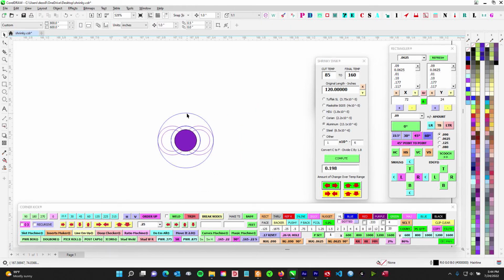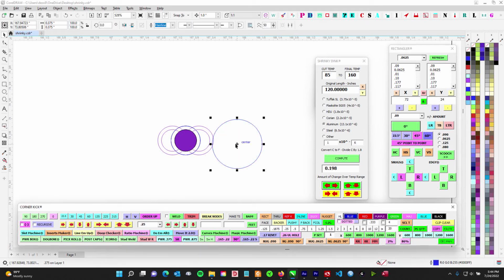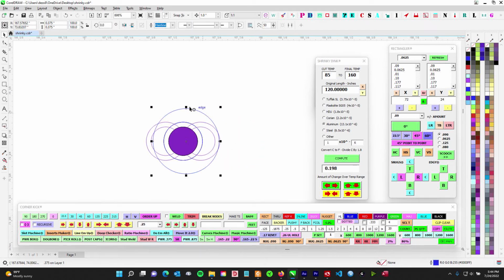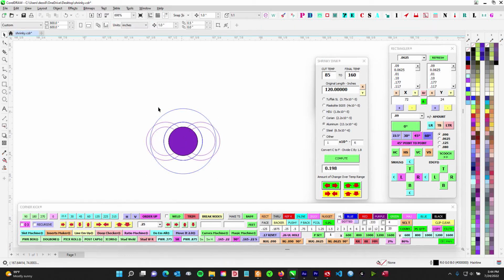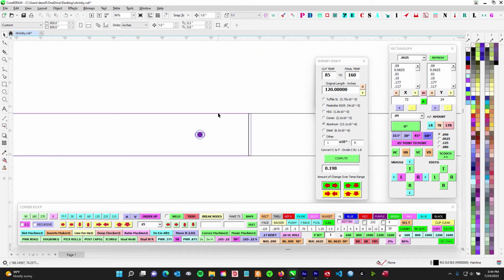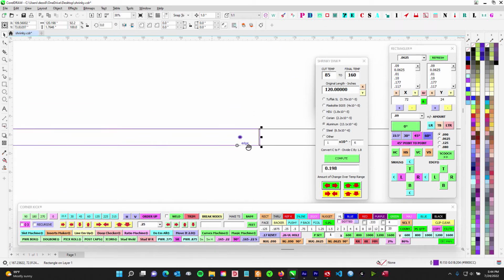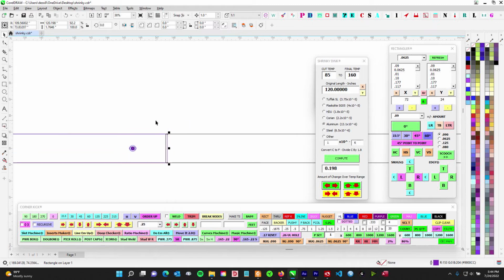So if you were to drill, this is a 0.4. So if you were to take like a 3/8 drill bit, now let's just go ahead and do that. I'm going to hit a 3/8 hole and hit blue. So you can see if you take a 3/8 drill bit and do your hole in the stucco or block or whatever, and then really silicone the crud out of it, you can see where you might have enough room for a bushing. But the fact that you're using aluminum will also mean that it's strong enough that it's not going to rip itself out. So you have a better way of doing that.